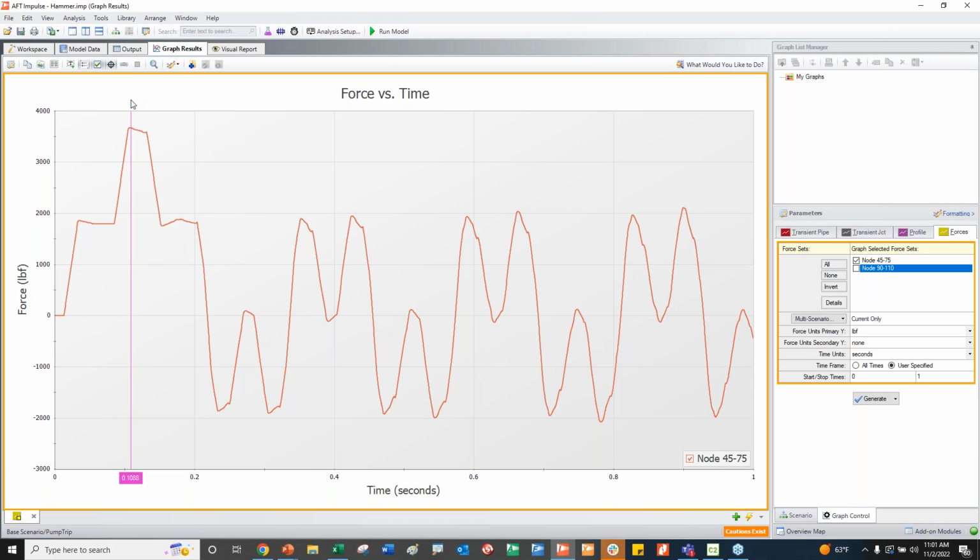If I'm not going to perform either a spectrum or time history analysis, I'm doing the static equivalent. You can apply the maximum force with a dynamic load factor of 2, because that's generally what is done. You apply it in your static analysis.